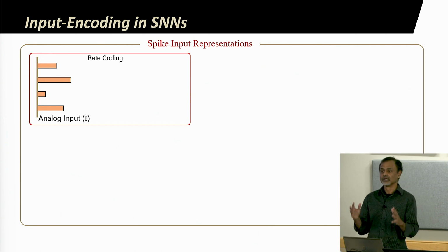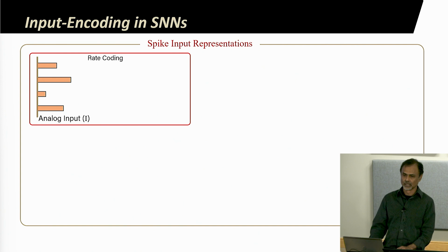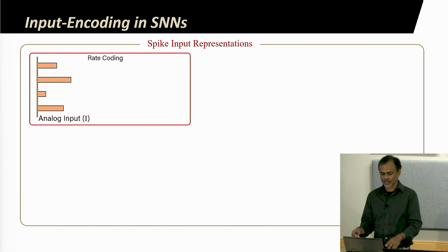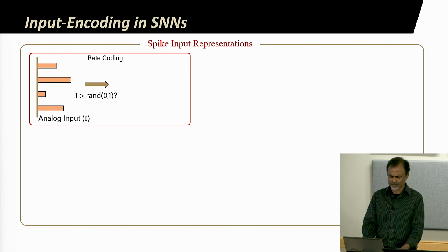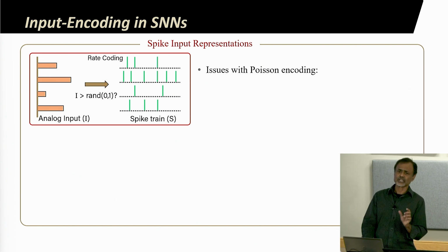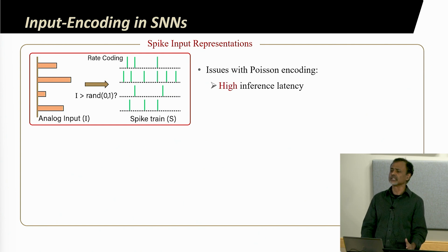Else, if the spikes are not generated, and the inputs are, for example, analog values, then there's a need to think about making them into the spike domain. People have done different kinds of representations of those analog inputs, coding them in a rate coding fashion using a Poisson spike train. However, representing inputs as a Poisson spike train is usually associated with a high latency.